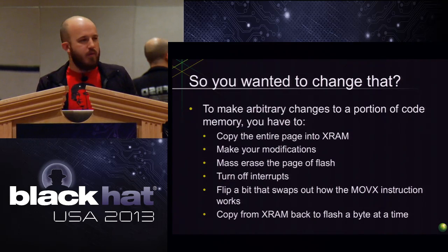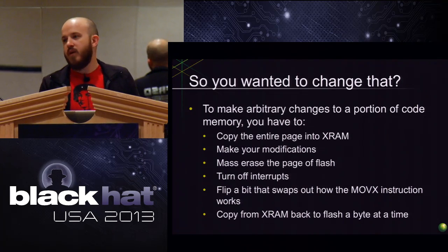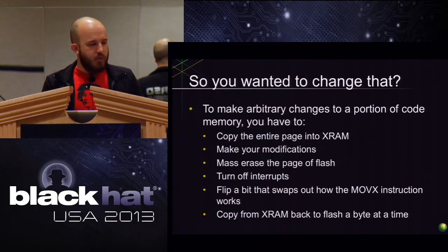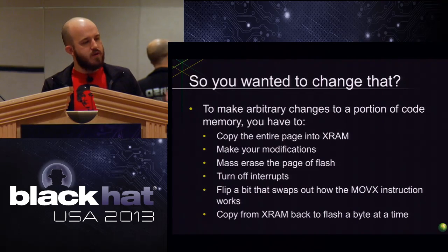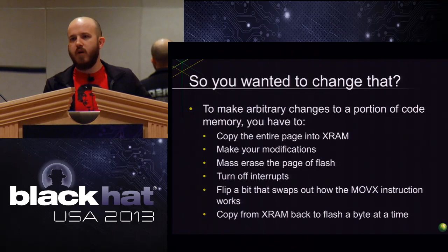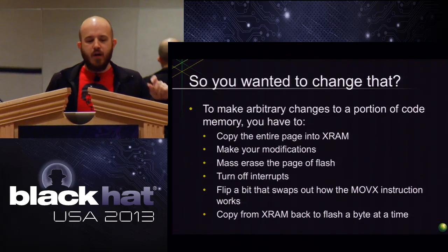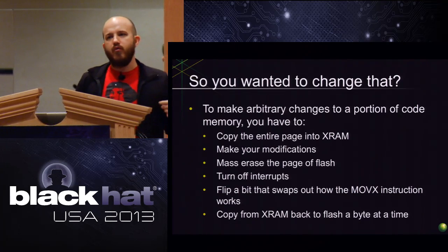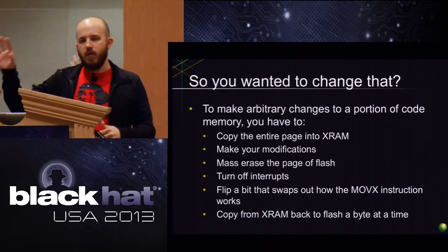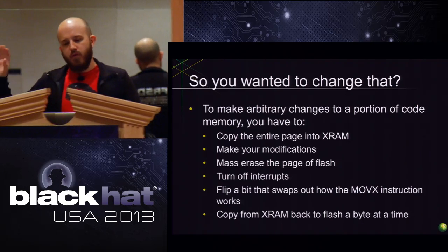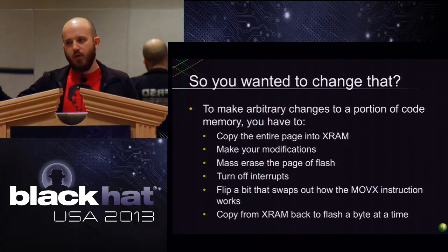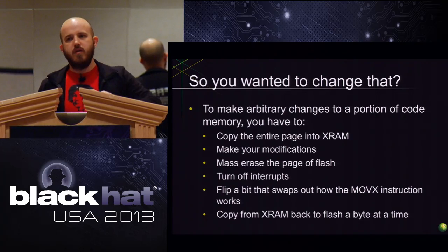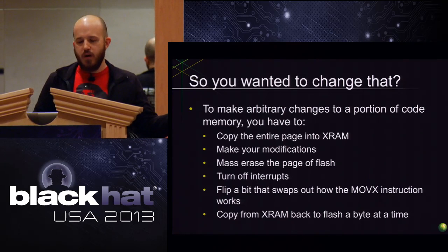The other things you have to do, like I mentioned earlier, you have to make sure you turn off interrupts and turn off CE, things like that, because it'll step on you right in the middle of it. The way this particular Harvard implementation works, like I mentioned, normally you can't ever modify the code page, you can never modify Flash. There's this movex instruction, which normally means copy data to or from X data. X data being a very particular section of memory, where all the data is stored, like all your variables and all that kind of stuff, not code. And you flip a certain bit, and suddenly that same instruction now makes a modification to the Flash memory.